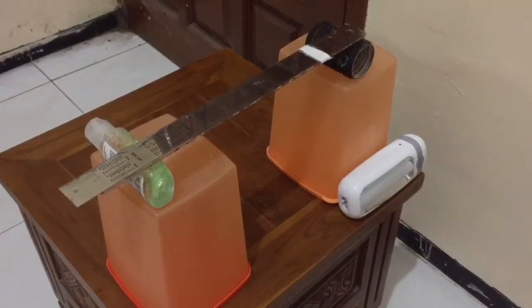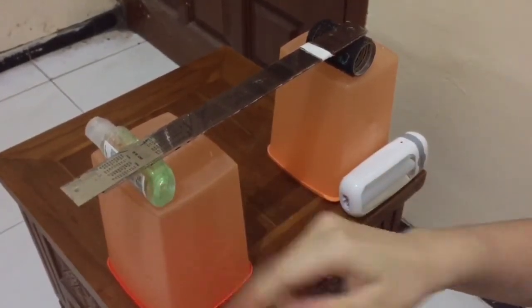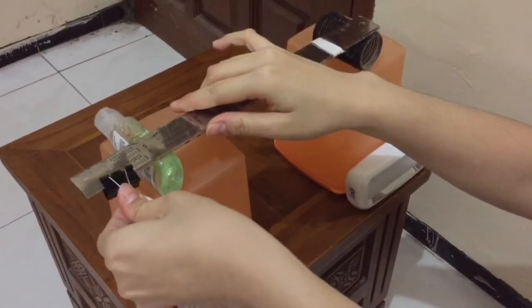So next I will explain to you the procedure of how to conduct the shear force experiment. Let's assume that these are our equipments, where this is our beam with supports on this side point B and this side point C. And we have a cross section here at point B, this white line here. Firstly we have to make sure that the display meter here is set to 0. After that we will apply various loads on various positions. First, we apply a load of 100 gram of mass, 40 mm away from point A. Let's try to put it.